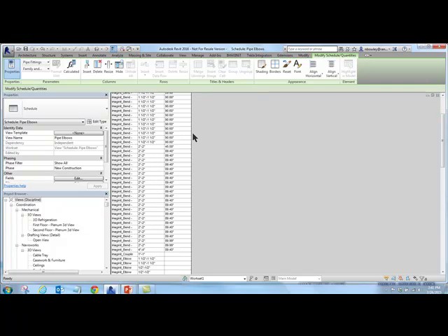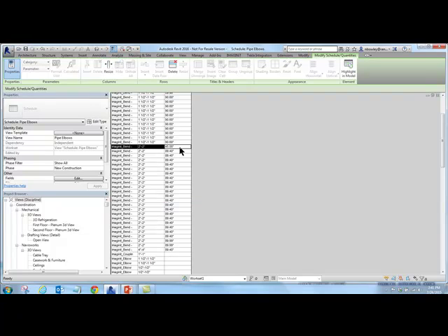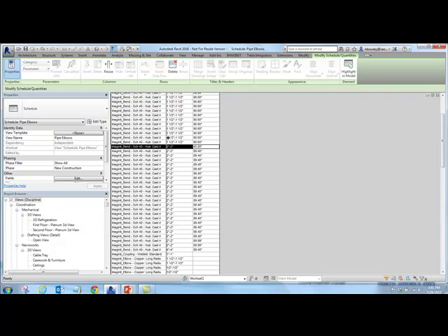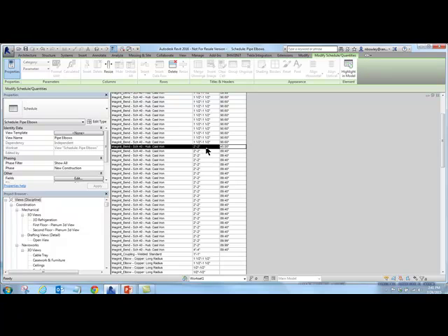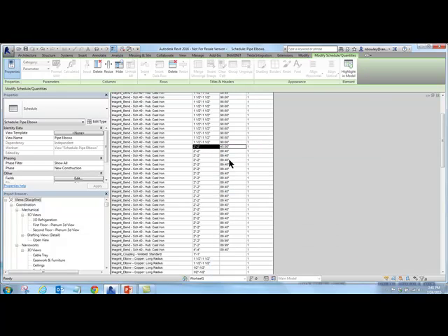There's a lot of weird angles in here. So there's my 45-degree angle one, and then the rest of them, they're slope pipes, so I guess their angle's just slightly off. So they're essentially 90-degree elbows. But there's my 45-degree angle, so if a contractor was trying to do takeoffs on how many PVC or cast iron hub elbows on a 45-degree, he can do a count. And of course, he'd have to hit the count column. In my case, I only have 1.